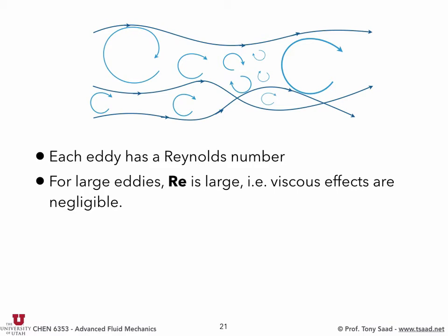And then as the eddies keep shrinking in size, the Reynolds number is changing. They reach a point where viscosity becomes important, and they dissipate the energy. Okay. So one way to think of turbulence, like I alluded to last time, is that nature doesn't allow for instability to happen, for perturbations to grow indefinitely. There should be something that will stop these perturbations. An explosion, for example, is something that stops an instability.